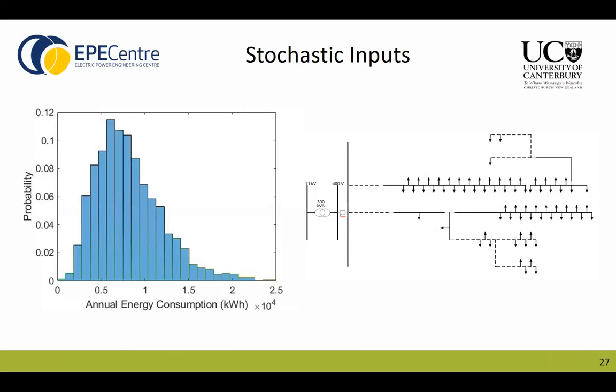Similarly, the placement of EVs can have a significant impact on load flow results, especially at low penetration levels. If you look at the network here, say a low penetration level that constitutes roughly 10 EVs within our total 71 connections here. If I randomly place those EVs, and it so happens that a higher percentage of them are towards the end of these feeders, then the load flow results provide slightly more extreme voltages than would be observed if we place those EVs towards the beginning of the feeder. So EV placement was another stochastic input to our simulation.